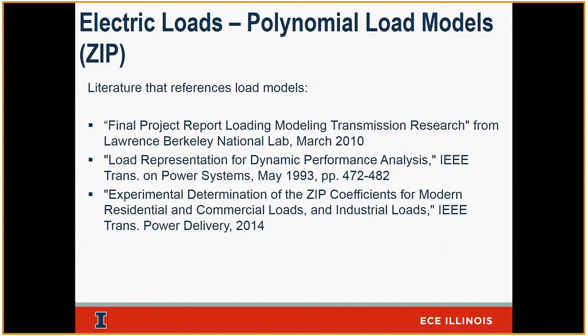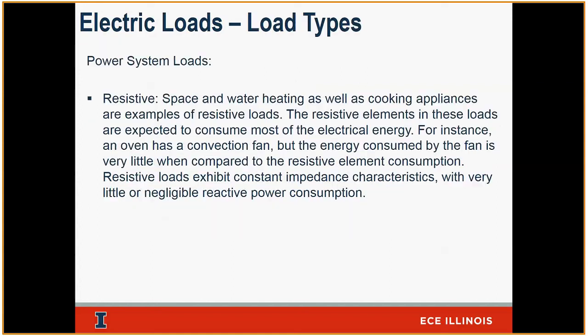So if they did refrigerators, do they get a cross-section of refrigerators and average them, or go, this is a new efficient one, this is an old one, or? Yeah, that's a great question. I think they bought multiple, so they would have bought an old one and a new one. For lighting, for example, they did the fluorescent lighting, they did the CFL lighting, they did the LED lighting, and they will have a characteristic for each. For fridges, I think they bought three different ones, and they averaged them together. So they calculated the zip coefficient for a fridge based on these three that they bought. Fans, same thing. But things that are a little bit more detailed, like the lighting, they were able to break those down into their own components.